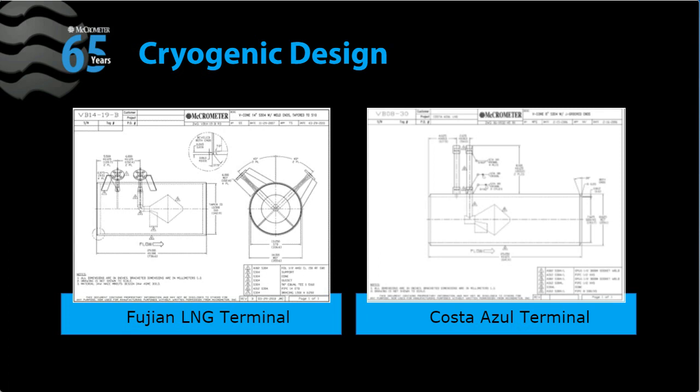This was built with beveled ends, so it was welded in place, and it had rotated sets of taps. We're able to do all of this, whether it's a rotated set of taps or tap bracing, because V-Cone is an engineered product, so we are building it to match whatever the client's specifications are. Whatever the client's piping spec is, that ends up being our piping spec.